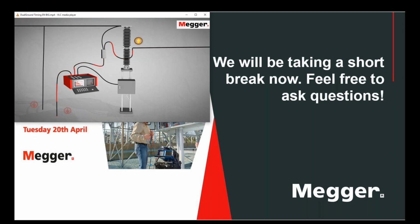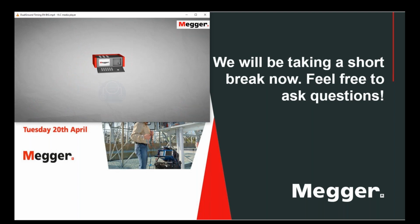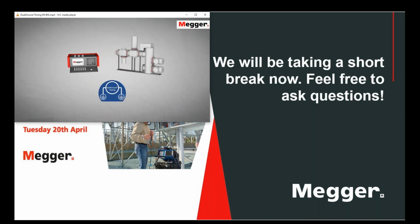With Megger's dual ground method, the circuit breaker can be timed without removing the ground, which makes the test both safer and faster. With the TM1800 and the dual ground method, you can also time gas-insulated switchgear and generator circuit breakers without removing ground connections.